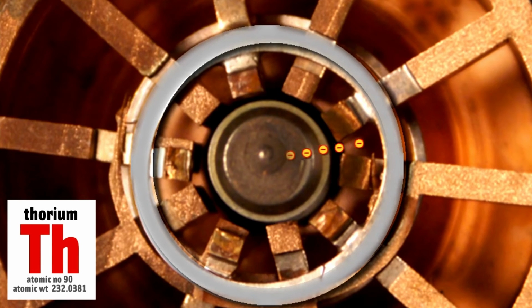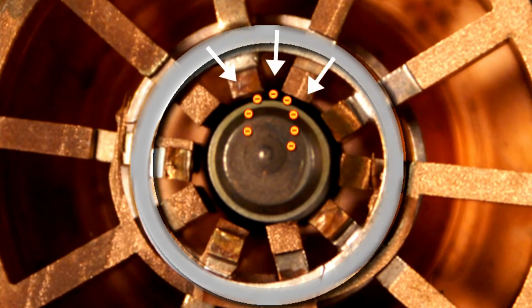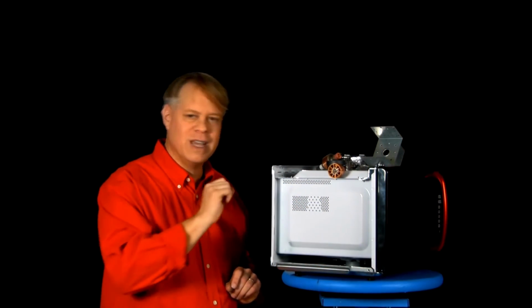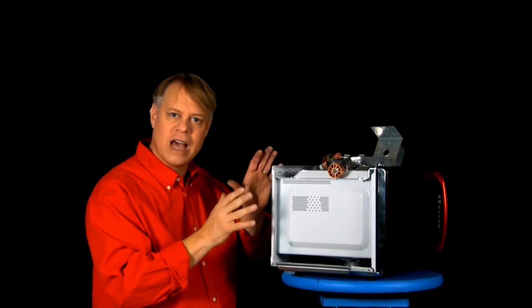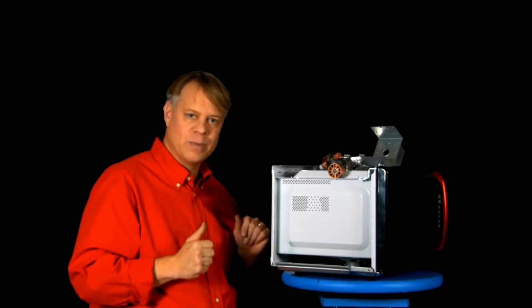The magnets bend these electrons so that they swing back toward the center filament. We adjust the magnetic strength so that the now orbiting electrons just brush past the opening of these cavities. Like blowing over a half-filled pop bottle to make it whistle, this creates an oscillating wave, the microwave radiation that heats food. It's simply astonishing that these cavities can be made with high precision, low cost, and incredibly high reliability.